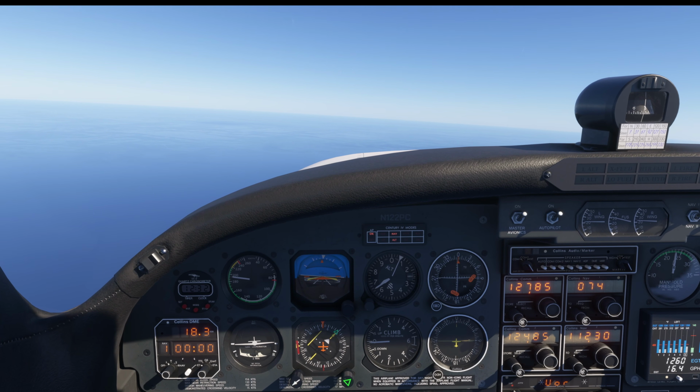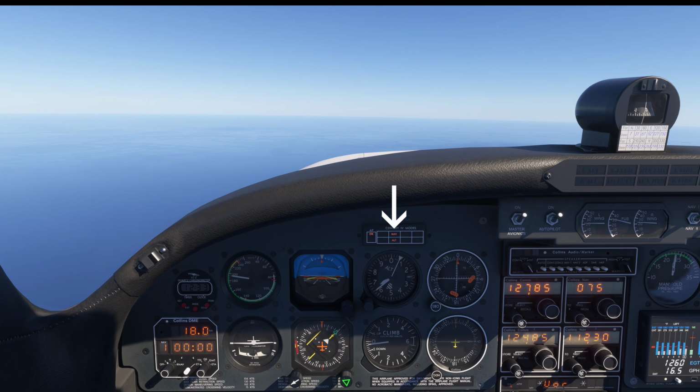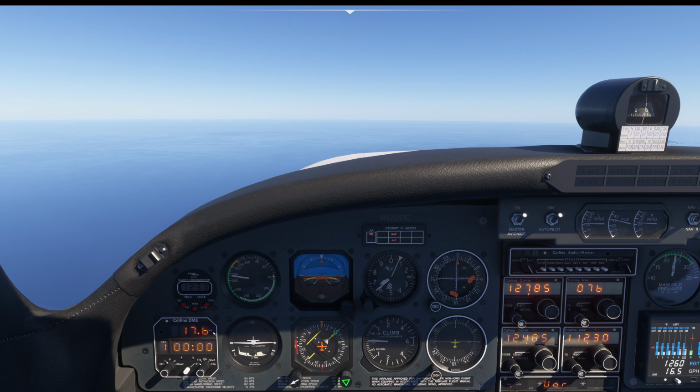This is how the real autopilot works, and this profile is used every time you activate nav mode, no matter what is the distance to the beacon or what is the aircraft ground speed. The autopilot simply does not know that, so in some situations it may overshoot and hunt the needle, especially if you are close to the beacon and flying fast.